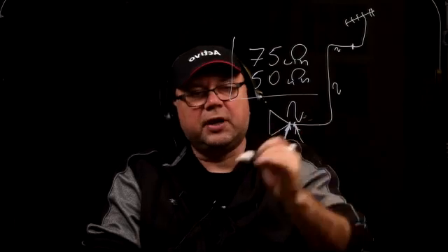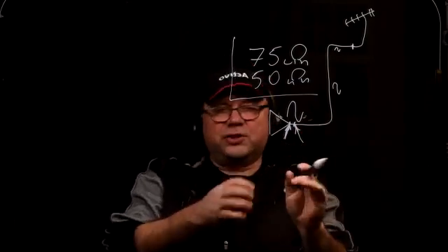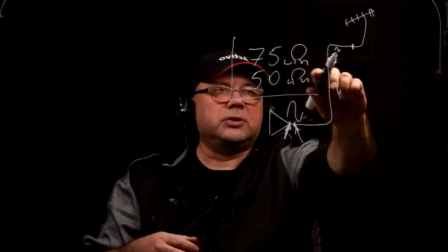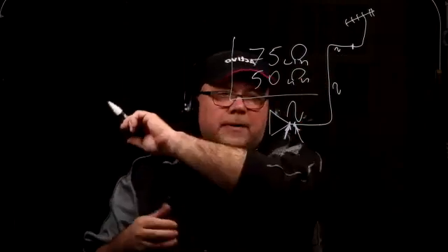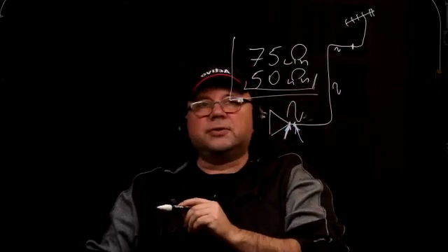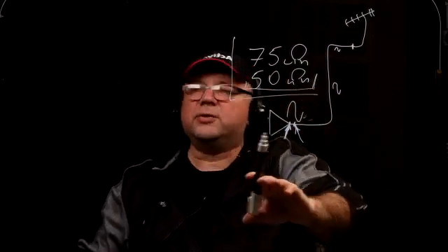So for the maximum power transfer, you need to have the impedance of the output of this equipment equal to the impedance of the input of whatever it is. In this case, it's a coaxial cable. All the impedances have to match. Right? So if you have a radio frequency amplifier that has an output of 50 ohms, you need to use a cable that is 50 ohms characteristic impedance. If whatever it is, 75, you get the idea.